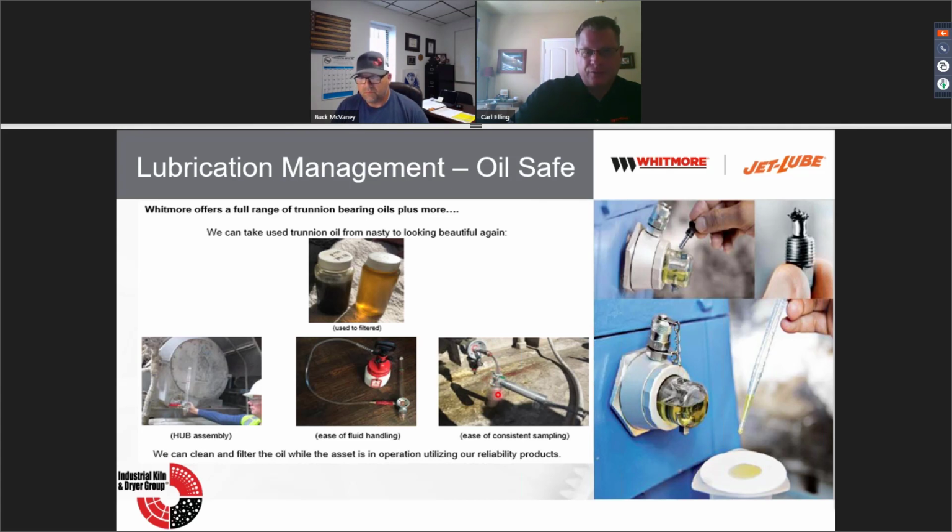So as you can see, this sample, we still haven't quite gotten to the cleanliness level that we wanted to achieve. But when we were all said and done, this was the result. And it's really nicely done. One thing, a caution of error. This particular tube is acrylic. If you're using a polyalkylene glycol synthetic oil, it will shatter this thing. It'll crack it up. So I would use a glass type for the sight tube. That's one thing that we learned during that whole exercise.